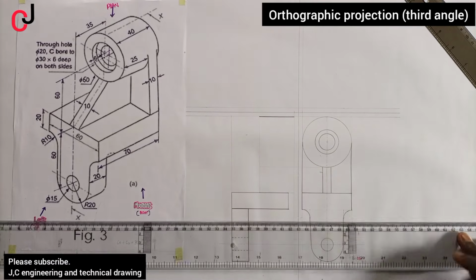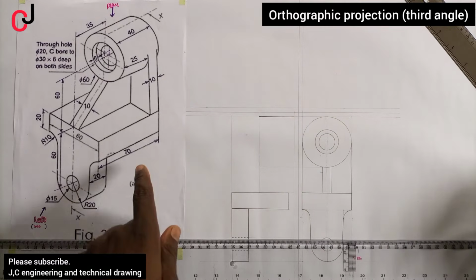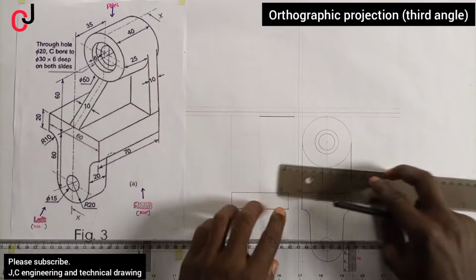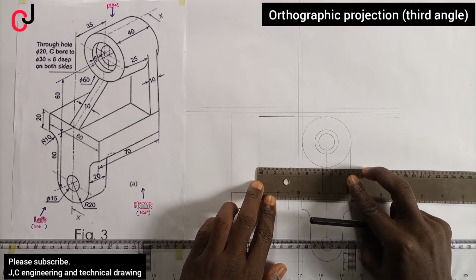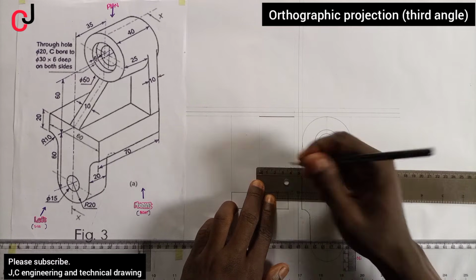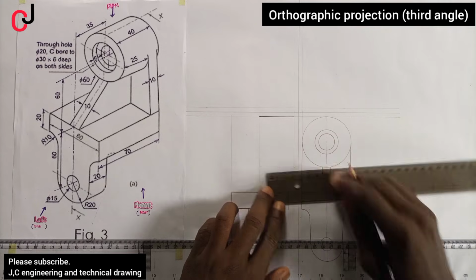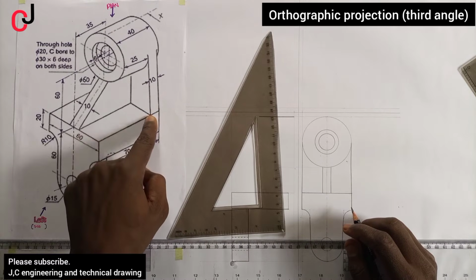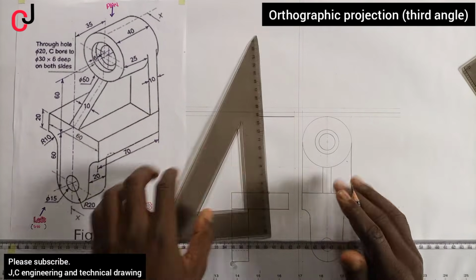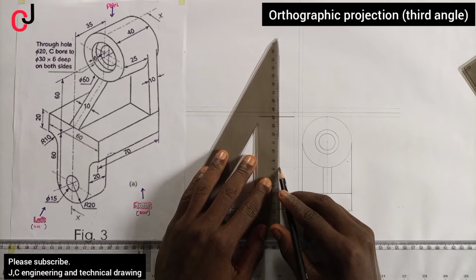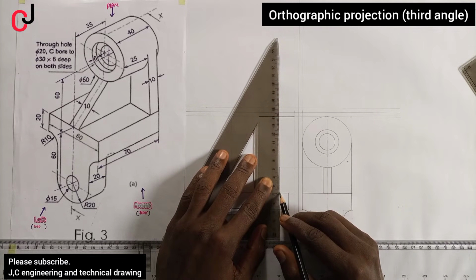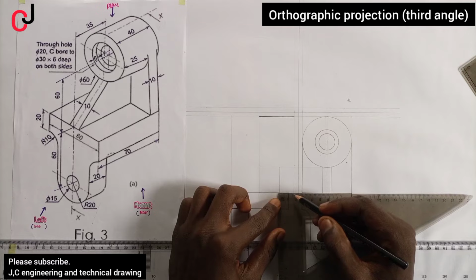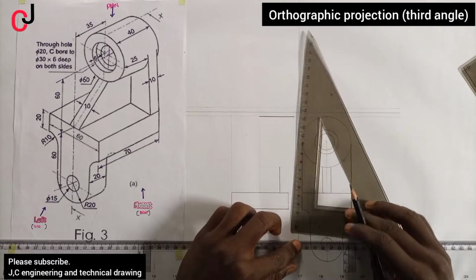Okay, you leave this a little bit. So now you say from here to here is 25 millimeter. So we'll measure 25 millimeter, and then we indicate it to the point, and then we'll project that point downward because it came down here. Here is 10 millimeters, so you project it downward. You should measure 10 millimeter, which is this, also 10 millimeters. So project up.